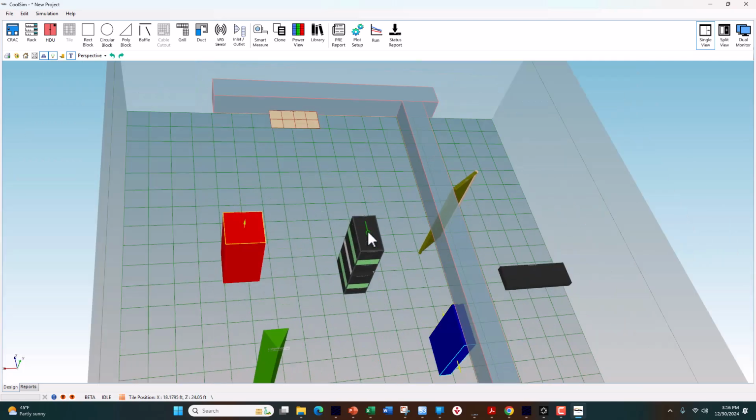We have very nice tools to help you along the way, such as Control-C, Control-V of objects, so you can duplicate them. We have a grouping feature, so all I did there was point at an object and used Control-C, Control-V. We also allow grouping. So you can group 2 objects together. I just held my left mouse, used the control key to select both of those objects. Then I can right mouse it and group it, and now it's an entity, or an assembly in this case.